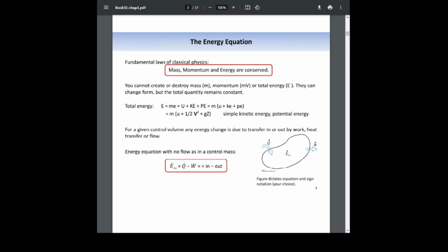So when we have a control volume with a constant mass, the equation can be rewritten like this. And if we write it as a rate, this is like a closed system, we would have the rate of change, dE/dt. Essentially, this is the rate at which energy is changing in the system, equal to any heat coming in minus the work going out. So typically this is just what's coming in minus whatever's going out. But this is for a closed system, or essentially a constant control mass.